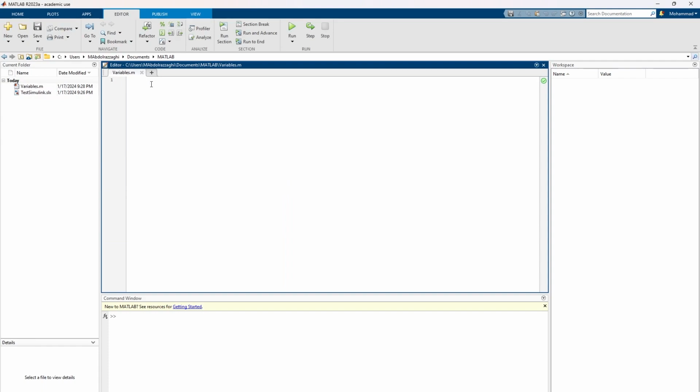What I need to do here is add some lines of clear all and close all. The first one clears all of the variables that have been used in the past, and the second closes all of the open windows and figures. And in order to create a first order system, we need to have k as the factor that shows up in the numerator. I would call it the capital K that equals 1 in our case for the time being. And I need a tau, which is the time constant of this first order system and shows up in the denominator. I would then call this tau equals, for instance, 8.